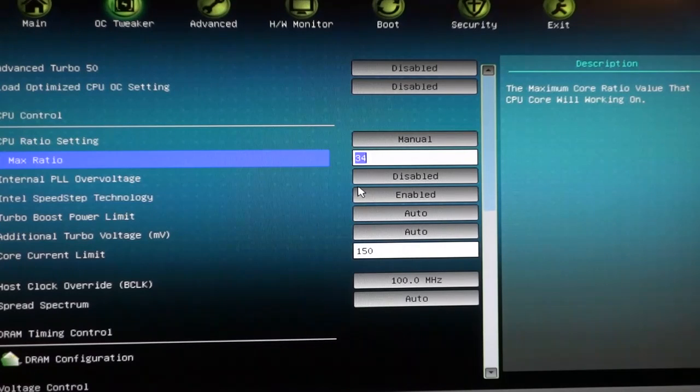able to run at. You may have already tried changing these settings. You might have had a reasonable amount of success. A lot of people, particularly with this processor or the 2500K, could change that to 40, giving you 4 gigahertz without the need to change any other setting in the BIOS at all. But at one point you'll start to find that you'll be having trouble. Perhaps your multiplier is automatically throttling down for no apparent reason, and that's where we're going to start with now. I'm going to enter in here 44 to give us 4.4 gigahertz to start with, and then move on.